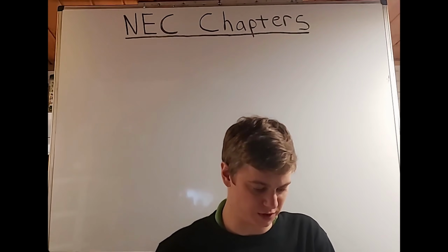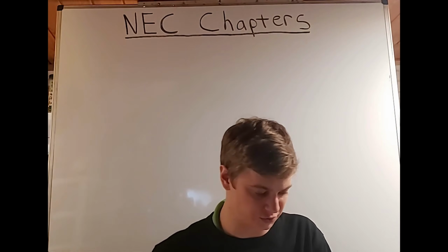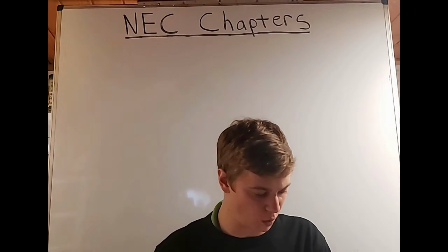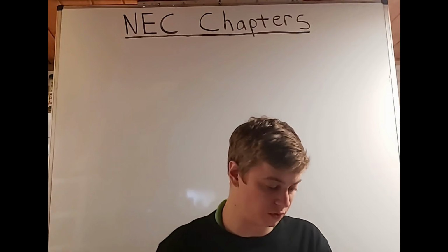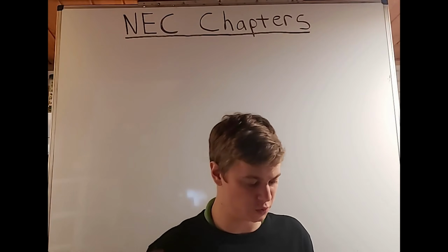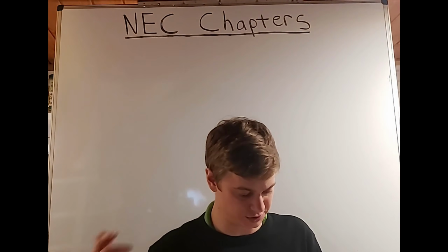2 is laundry branch circuits. You need at least 1 additional 20 amp branch circuit. 3, bathroom branch circuit. You need 1 or more 120 volt 20 amp branch circuit. Garage branch circuit. You need at least one 120 volt 20 amp branch circuit.